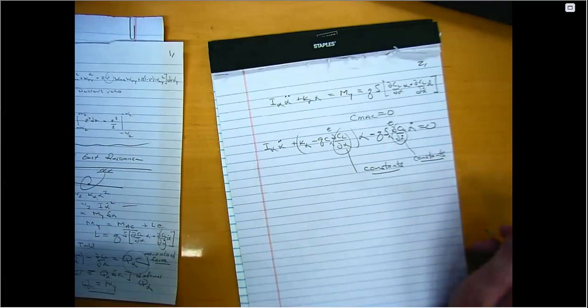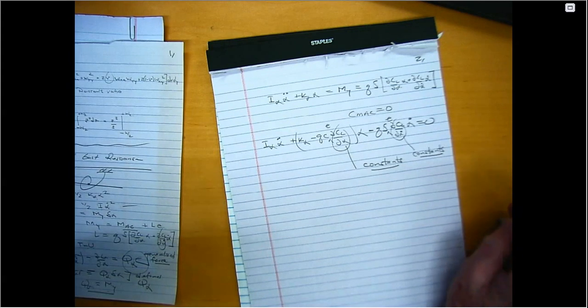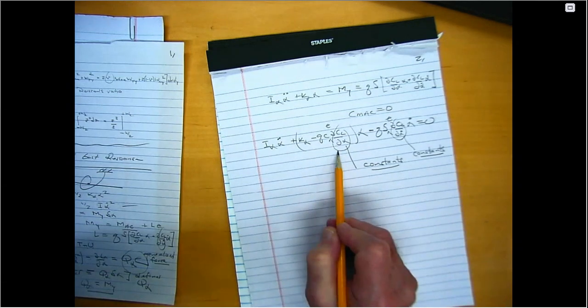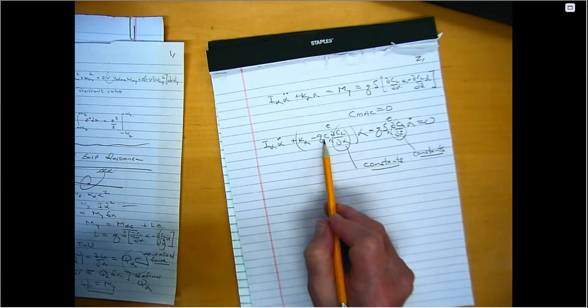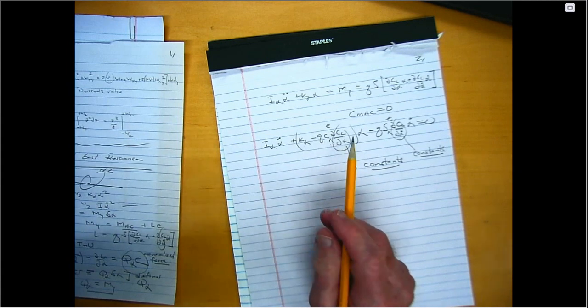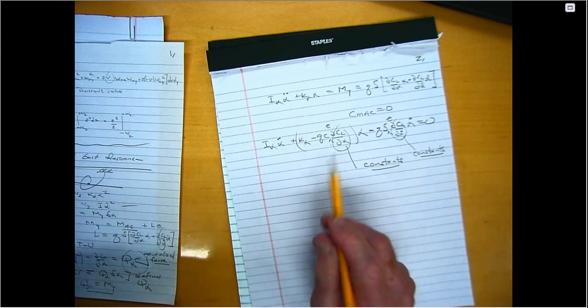Now, what can this equation tell us? Well, first of all, from a dynamic perspective, it can tell us that divergence is a possibility. Why is that? Well, this term can change sign. If Q gets large enough, this term will become negative, and that implies basically I have a negative stiffness. You might think that a system with negative stiffness would have a static instability.